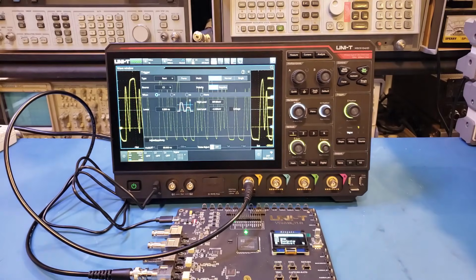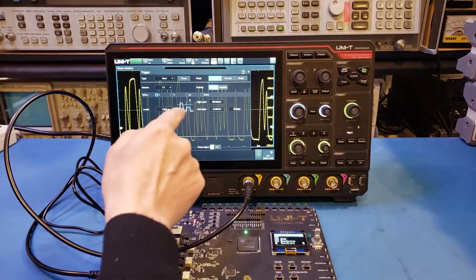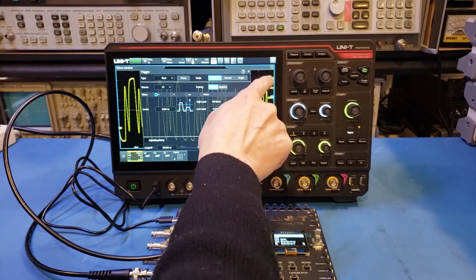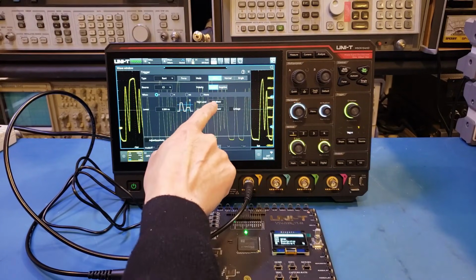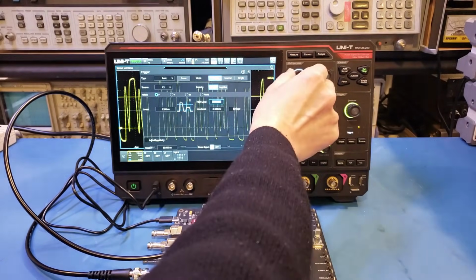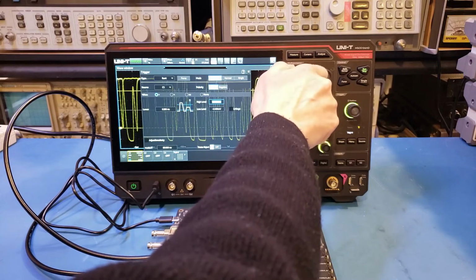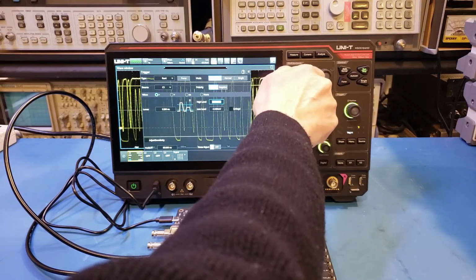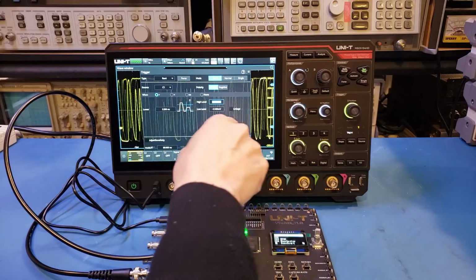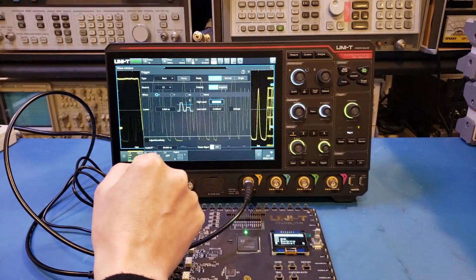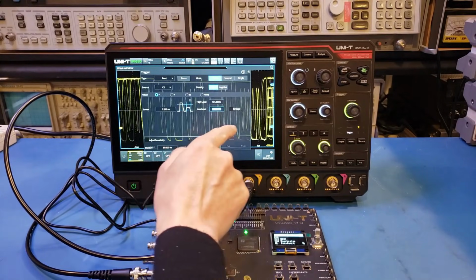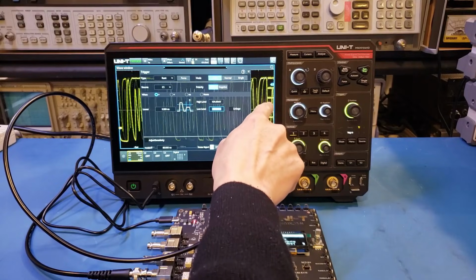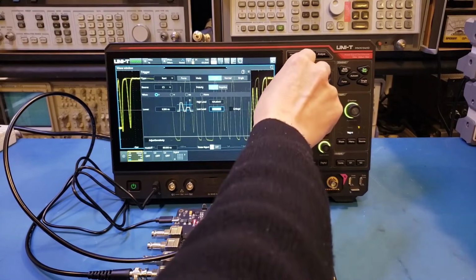And for the round pulse capturing, obviously you can set a high level. And here, let's actually set the high level to be 450. So let's do this. So that's our pulse. So that's for the higher amplitude pulses. And now we have a low level. So the low level here, actually, let's do maybe 250.